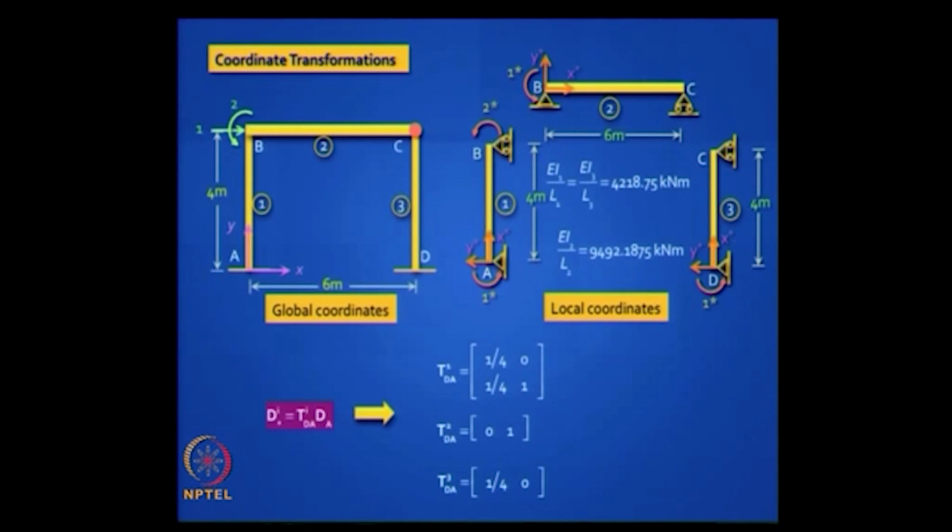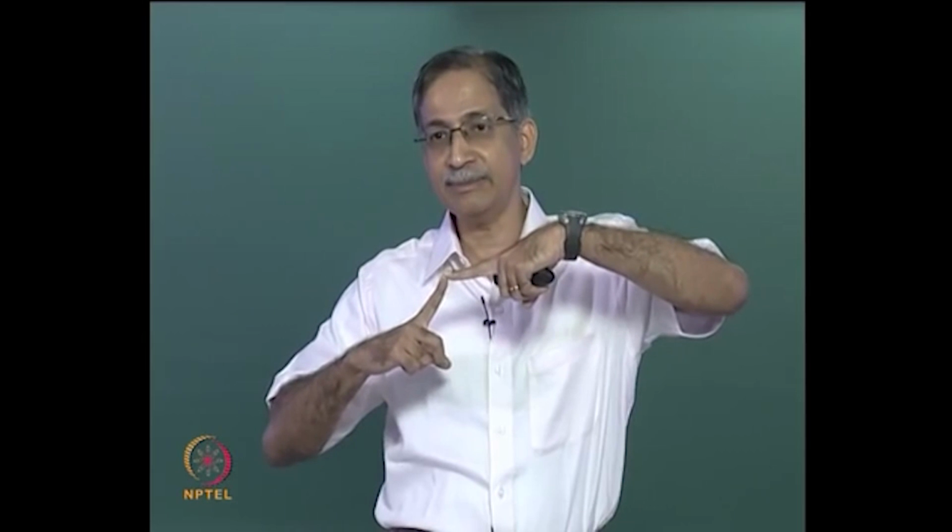This is the change. Another thing, in your global coordinates D3 is gone now, because you can't talk of D3 in your structure because you have 2 different rotations in the connecting members. So you remove it, you don't need to put a clamp here. Just remove it silently. So you have only 2 degrees of freedom.